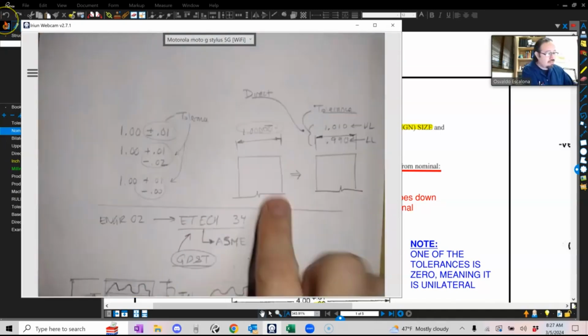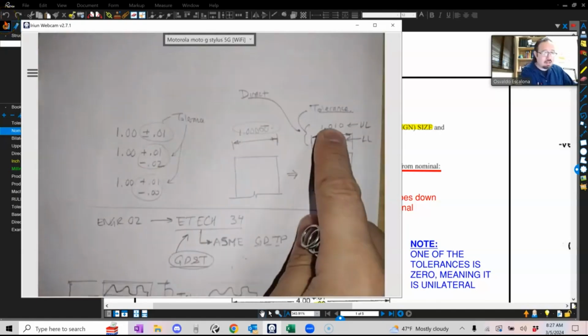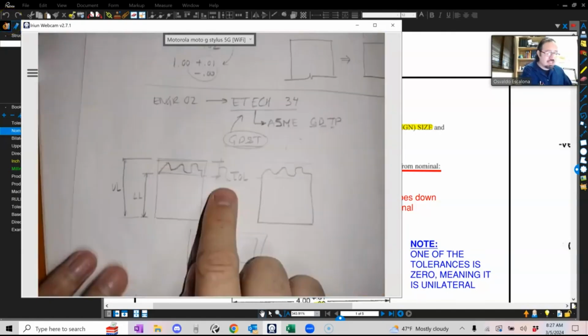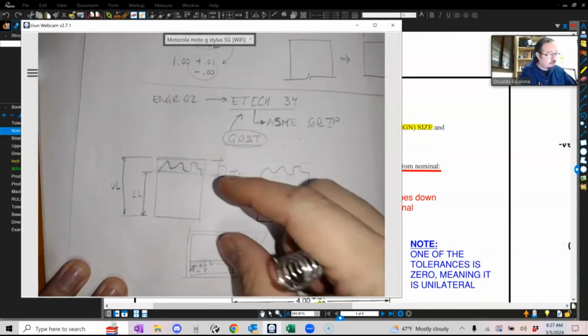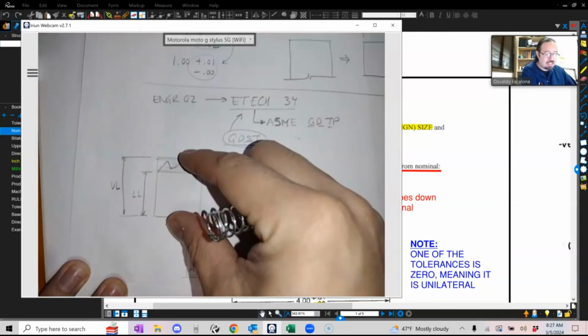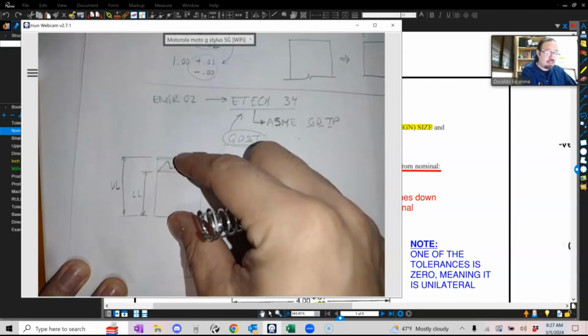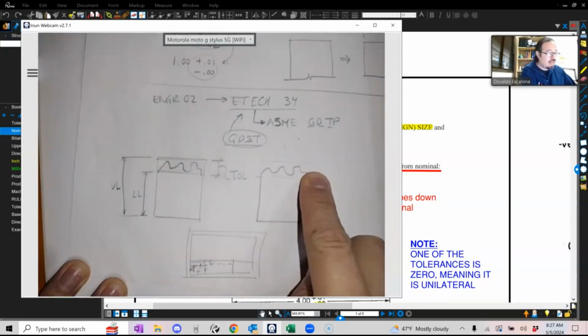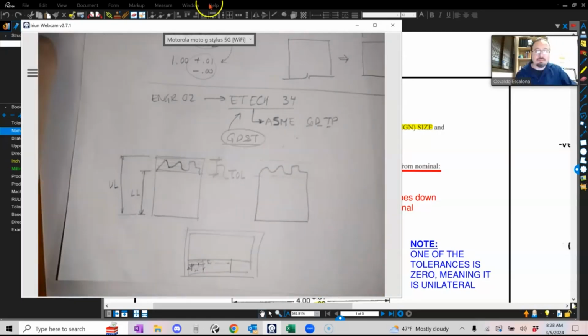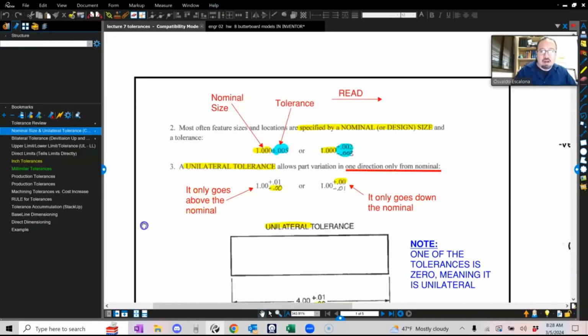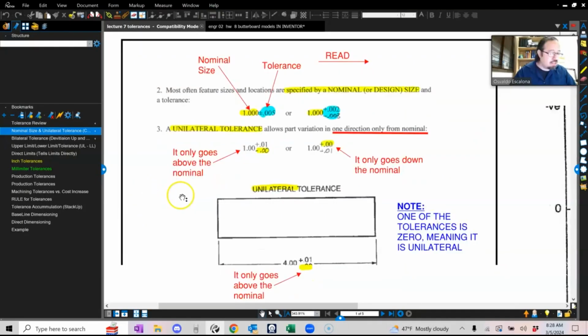And again, coming over here, you have a lower limit and an upper limit. The tolerance is this guy, where it could have form and variation in size and form. It can increase in size based on whatever my upper and lower limit is, and it could have a variation in form as long as I am within my upper and lower limit. Okay, let's call it unilateral tolerance. What's a unilateral tolerance? This is what a unilateral tolerance is.